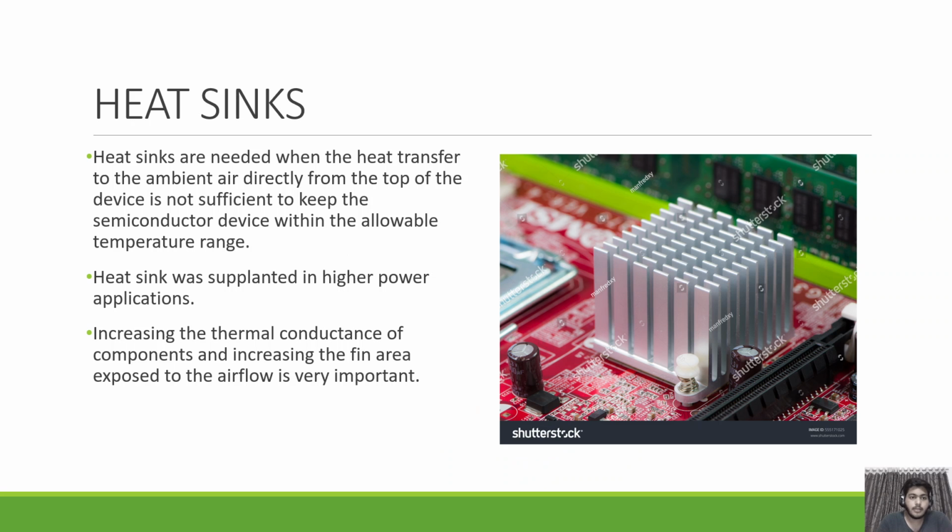Heat sinks are needed when the heat transfer to the ambient air directly from the top of the device is not sufficient to keep the semiconductor device within the allowable temperature range. Heatsinks are used in higher power applications; increasing the thermal conductance of the component and increasing the fin area exposed to the airflow is very important.